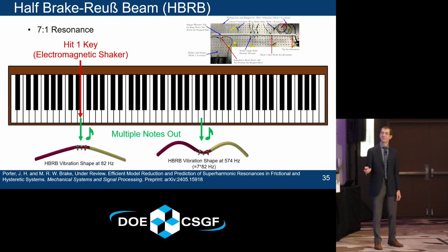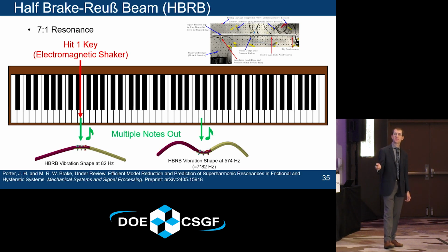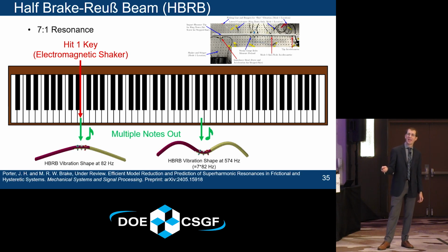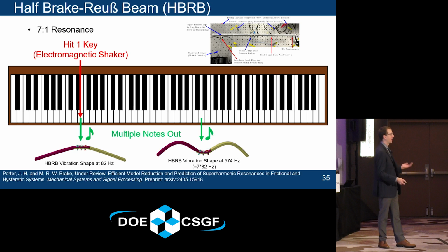So on a piano, this looks like you're hitting this first note with the electromagnetic shaker. And yes, I did look up the frequency of these keys on the piano. And you get this vibration shape at that frequency. Then at 7 times that frequency, or approximately this note on the piano, you get this additional vibration shape, even though the shaker is only exciting this first frequency.